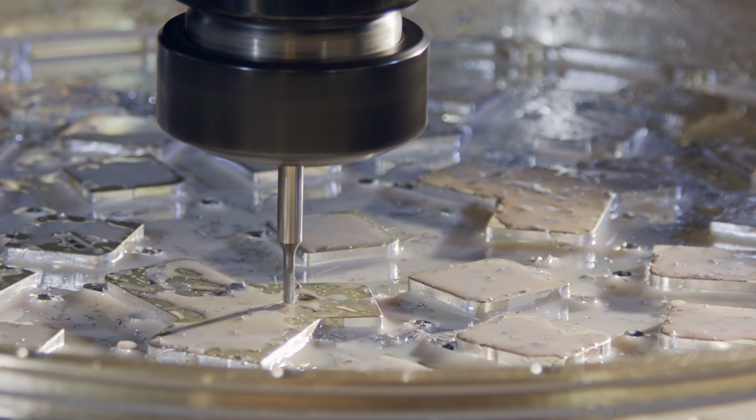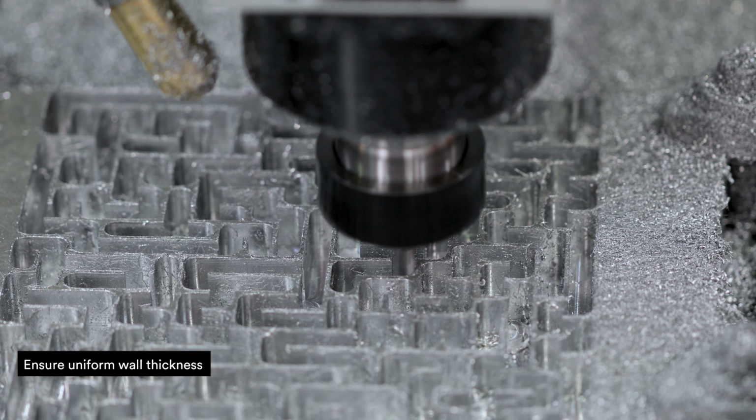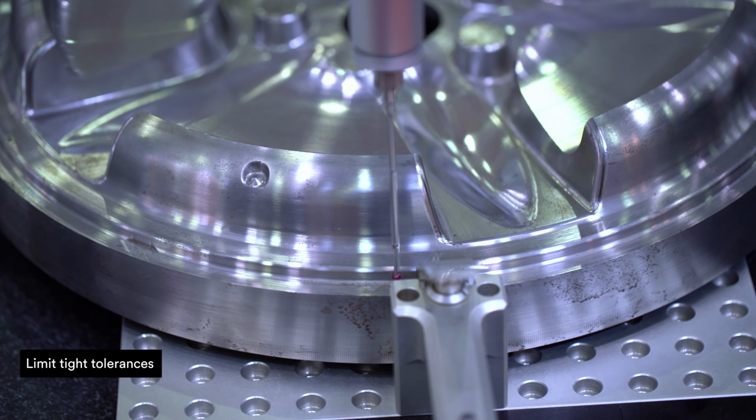Use common radius sizes to streamline the manufacturing process. This minimizes the need for custom tools and simplifies programming for CNC machines. Design parts with consistent wall thickness, ideally between 2 to 4 mm, depending on the material and manufacturing process. It's very important also to limit tight tolerances.